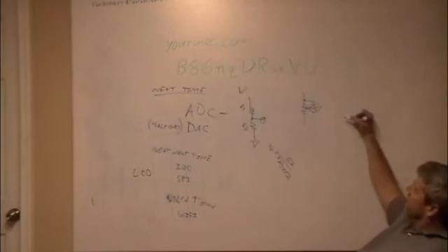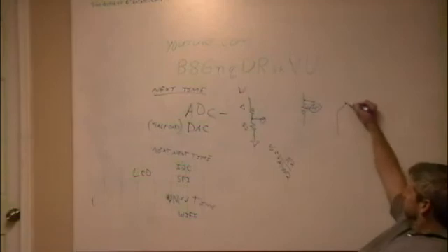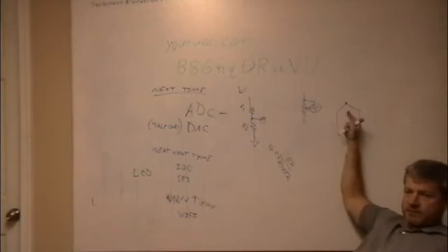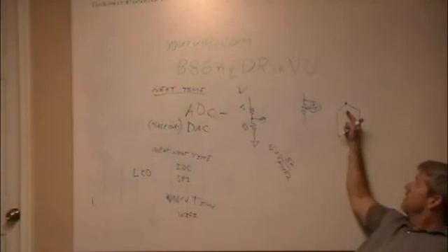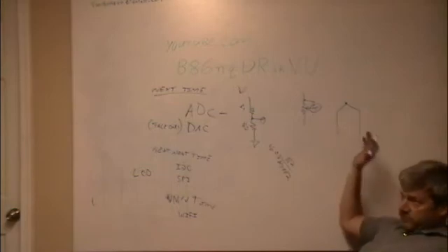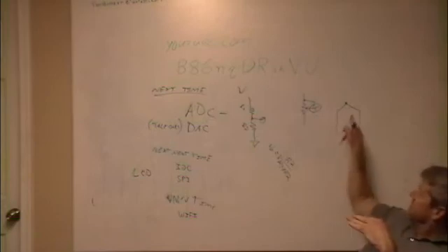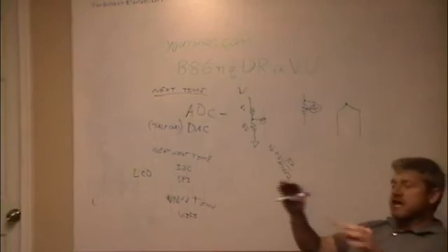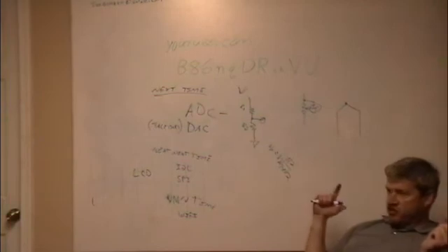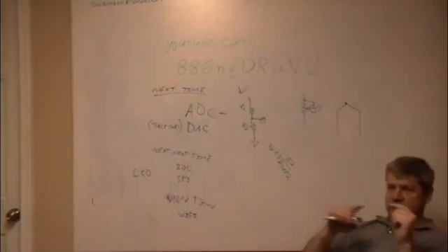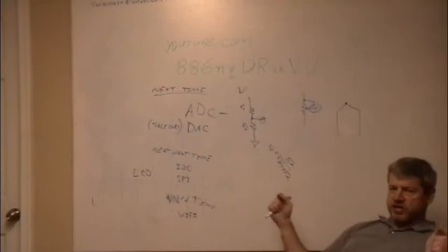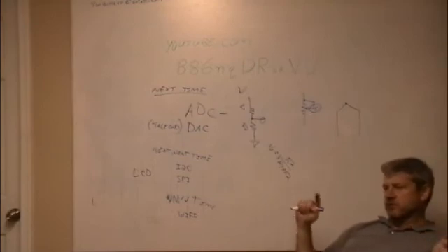So for a thermocouple, the drawing actually explains what it is. It's 2 wires welded together, and the 2 wires are made out of different metals. This is called, I think, the Seebeck effect. Let's back off. Any one metal has a Seebeck effect. If I change the temperature on this end, it's going to have a change in potential voltage across it, because of a change in electron mobility due to temperature between the 2 ends.